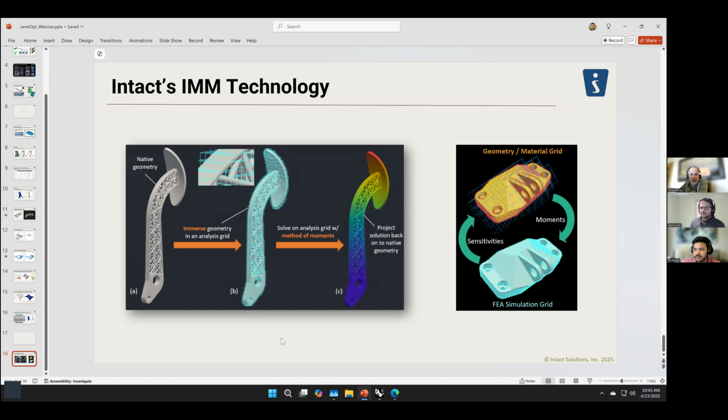Is there more information about the verification of the model and validation of the model for applications? As in benchmarking the simulation itself? Menno, if you can help us understand that better. But yes, we have benchmarked against standard FEA problems provided by NAFEMS, and against other commercially available software as well. And typically we see displacements within 1 to 3% and stresses around 5% or less, in a fraction of the time and at less expense. And then we can provide the benchmarking documentation if interested.